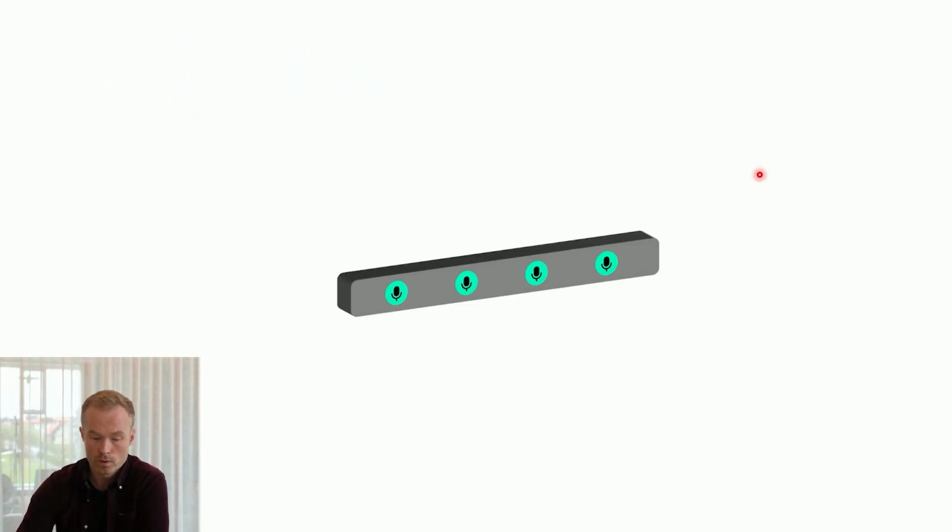So if we now look at this fictional device here, what you would have to keep in mind if you want to create a device for something like this is that ideally you want to be able to resolve the wave field around the device in a sphere that encloses the device. It doesn't have to be bigger than the device, like in this case, but ideally, if you want to capture the full effect, it needs to be around the entire device.